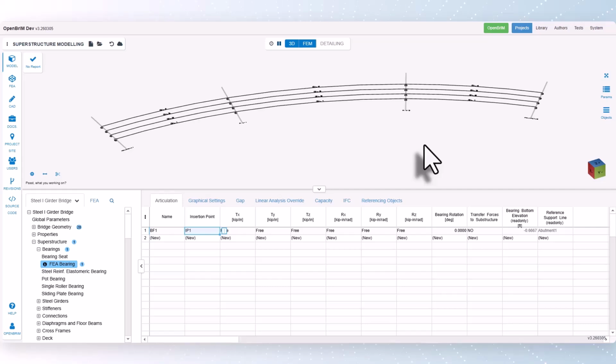For modeling purposes, using realistic stiffness values instead of idealized, fixed-free conditions is recommended. For example, if the substructure is not modeled and only the bearings are included, assuming fully fixed behavior will overestimate the actual system stiffness. When the substructure is modeled, using fixed conditions becomes less critical, since the substructure itself reduces the overall stiffness in the direction of interest.